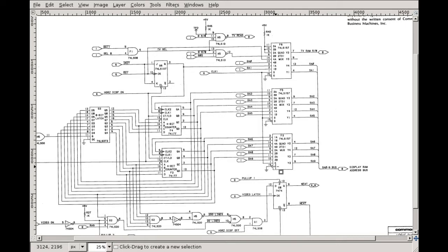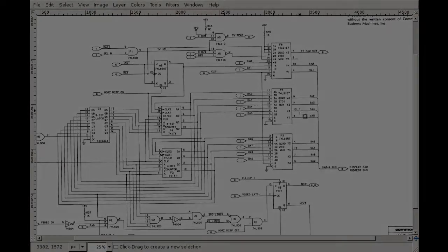When the CPU is not executing, these addresses from the CPU are of course not toggling, and also the data bus we have seen before on the CPU is actually three-stated when the CPU is not executing, and of course when the CPU is pulled from the socket, they are three-stated. So let's go to the actual board and have some checks on these signals and data bus.